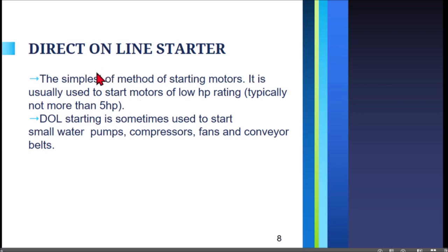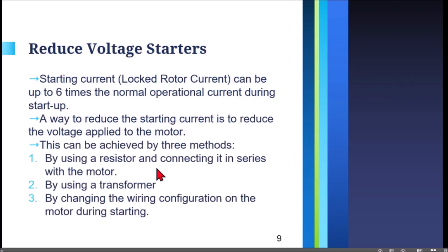So you could use the direct online starter on low HP motors, typically not more than 5 horsepower. Its main application is for water pumps, compressors, fans, and conveyor belts. Then we have the reduced voltage starter.